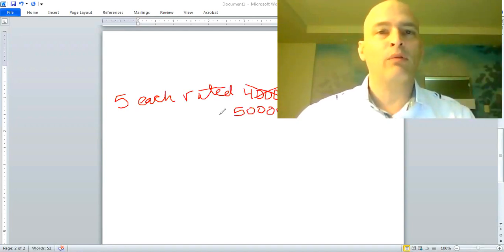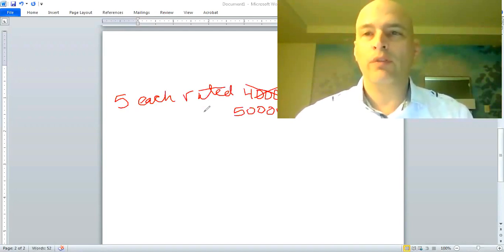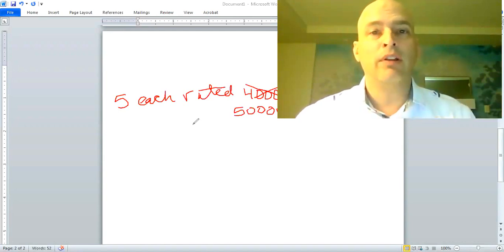That way you don't have to worry about remembering or keeping track of it. It'll be right there on top of the table when you go to use it later on if you do. Okay? All right, 5 times 5,000, since there's 5 of them, 25,000. The demand factor for 5 dryers is 85%. It's given to you right there on the table.